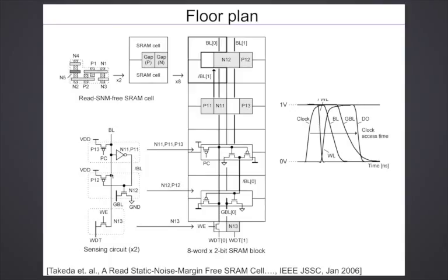In addition, you have this P12. P12 is what is called a keeper transistor. When I'm not doing anything, the pre-charge PC is kept low, so the PMOS is on, and all the local bit lines are pulled high. They're just kept high solidly. Before I do a read, if I decode my address and find that one of these 8 cells is to be accessed, I release this pre-charge so that this P13 is shut off. And if one of the cells pulls it down, good. But if the cell which I'm reading is not pulling it down because the contents of the cell is 1, then this bit line is floating for that duration.